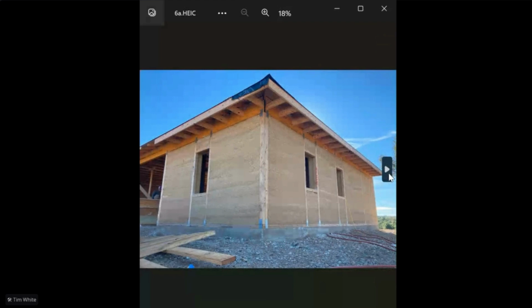Here's another example of that modified post and beam system with a post deck at the corners. There is the LVL on top. And so therefore that carries your header weight that you would normally in conventional building carry down over top of a window. And so you can get rid of that big fat header above the window and go to something simple like a simple 2x4. It works really great. And fairly easy to get through code because it's a pretty solid post pack system on all the corners and at the windows and doors.